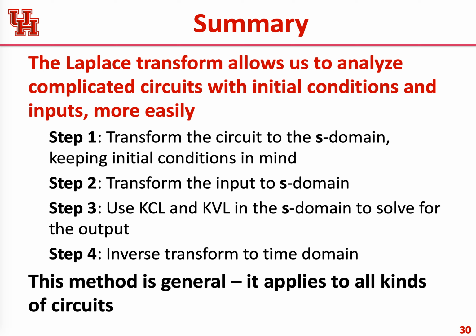The first part is to find the initial conditions, and in the second part you apply the initial conditions to all the inductors and capacitors, and thereby transform the circuit to the S domain. Then we transform the input to the S domain, and then we use our good old KVL and KCL. They work exactly the same in the Laplace domain. And then in the end, we can finally transform the answer to the time domain, in order to plot what it looks like.